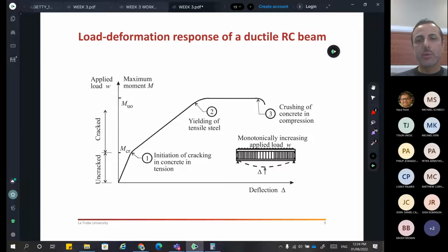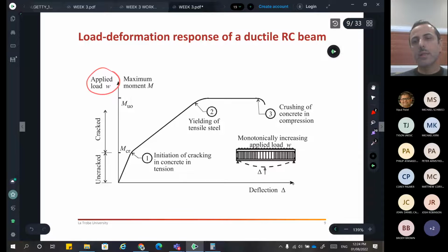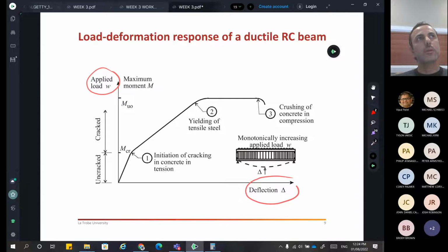It depends, again, on the level of load it is under. What we're seeing in this graph is a vertical axis, which is the load, and a horizontal axis, which is the deflection. As I said, by the time the fresh concrete or the new slab is sitting on the formwork, it's carrying nothing. We are here. No load, no deflection, obviously. Now, by the time we strip away the formwork, it will carry its own weight, right? And typically, by the time it takes its own weight, we're going to be somewhere here.